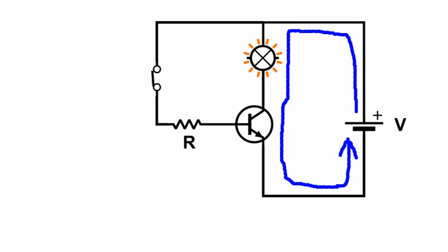The magnitude of IC depends on the base current of the transistor, IB. IB should be large enough for the transistor to enter saturation. When saturated, the transistor permits the free flow of current. In other words, it behaves like a closed switch.